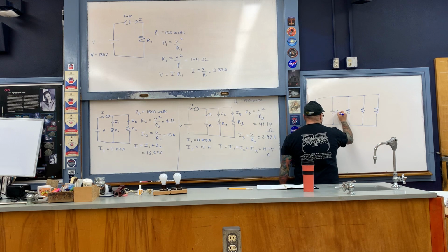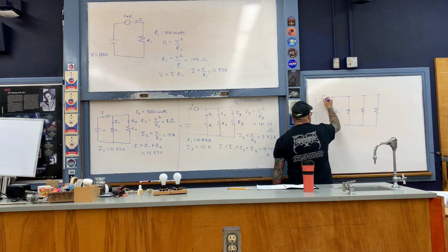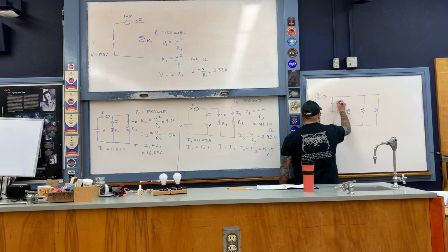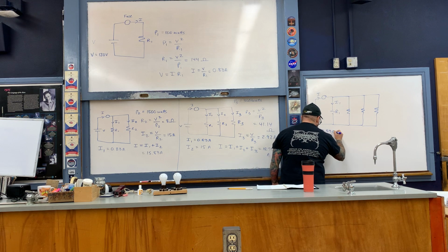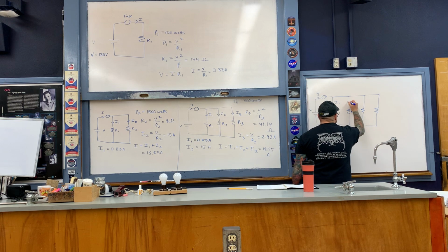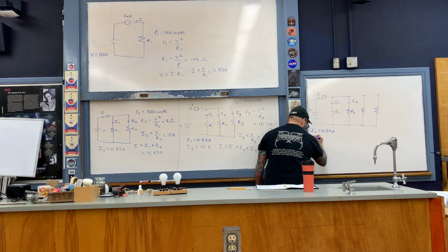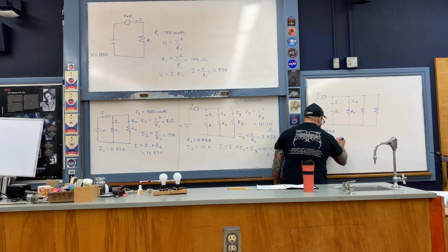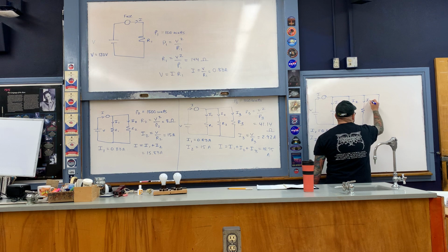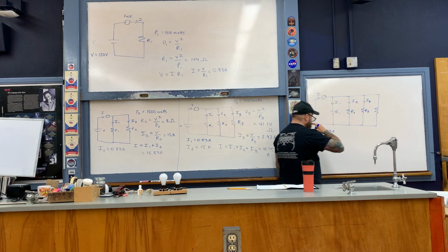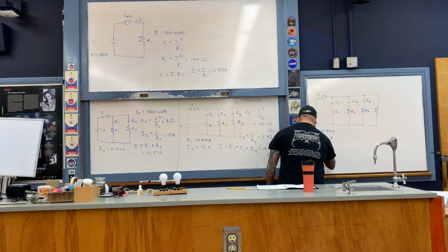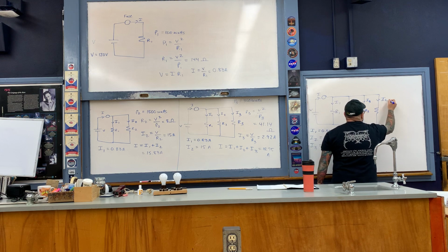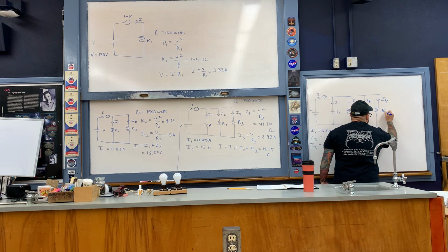So we still have here R1, here's the fuse again. Here's the current I. We still have I1 flowing through, that's still 0.83 amps as it was before. Here's the R2 with the I2 flowing through that, that's still 15 amps, just as it was before. And then we've got here now I3 from earlier flowing through this resistor. The I3, remember, was the 2.92 amps. But now we're going to have here an I4 that is flowing through this device.